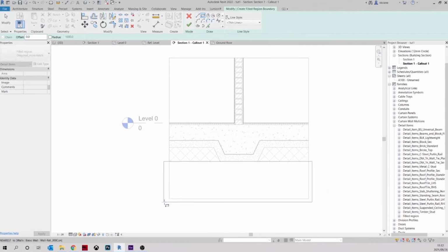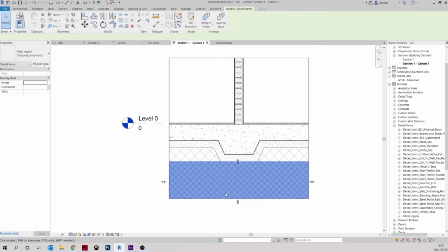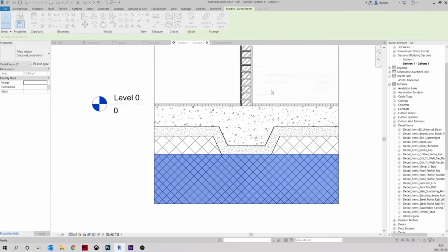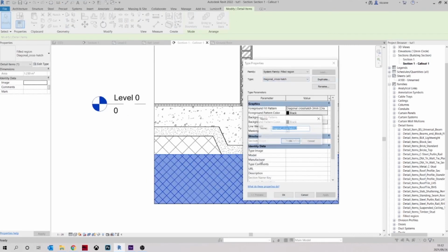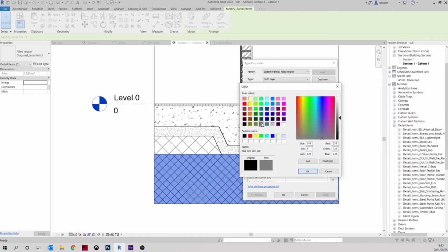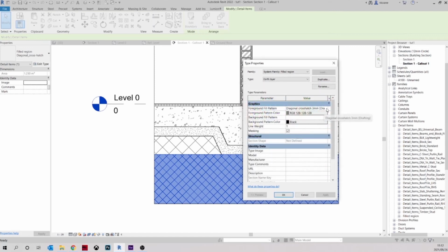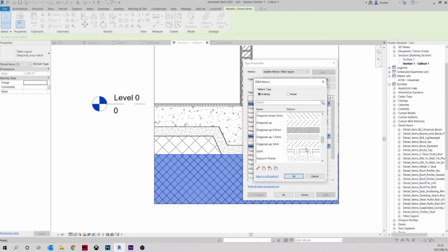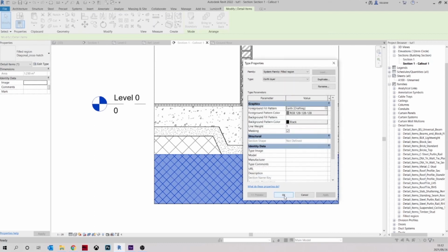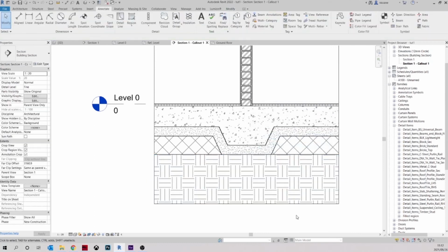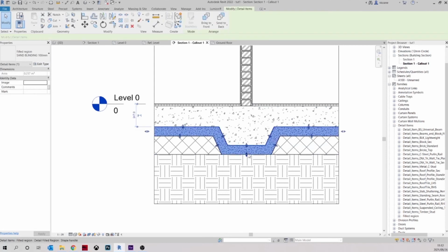We're going to make a rectangle like that, finish it, change the material, duplicate. Gonna name this earth layer, change it to gray as well, and look for an earth layer in your project. That's the scale I want. Let me check first. Let's see, that's what I want.